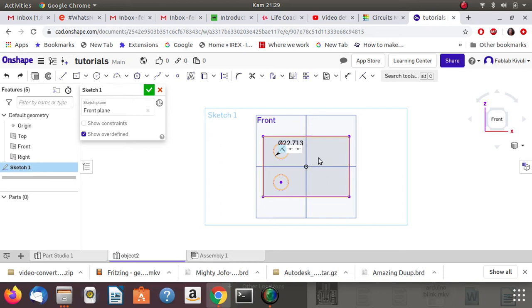Then we're going to start examining those constraints, but automatically it becomes parametric by nature, especially now that we put the constraint of this being mirrored along this line up to here. So if this changes in size, then everything else will be modified. So for now, let it stay in that format.